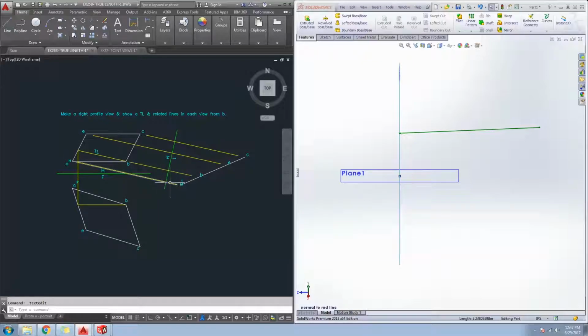If this is a projection line, if this is really just to connect these 2 points right here and show, oh, this one came from this one, you want to foreshorten them. If you actually had to make an intersection right here with a line in order to establish some sort of true length line, that needs to actually be touching the line of reference that you're trying to connect to. So this view is fully completed. We're looking at an edge view of this plane right here, and all of that was thanks to the true length line. So that was the hard way to go about this. Let's go the easy way.